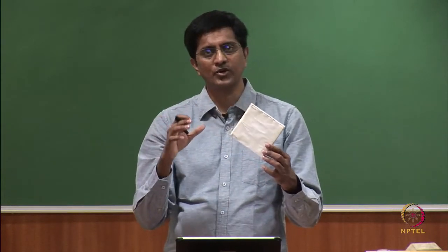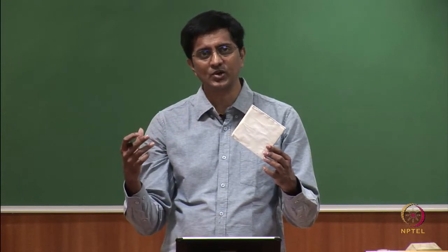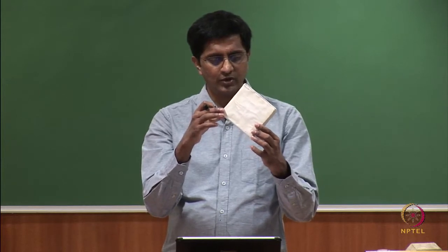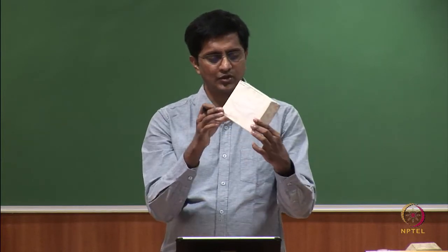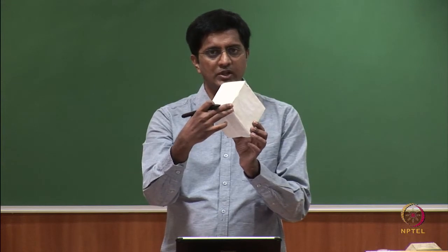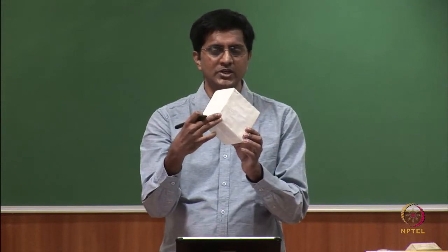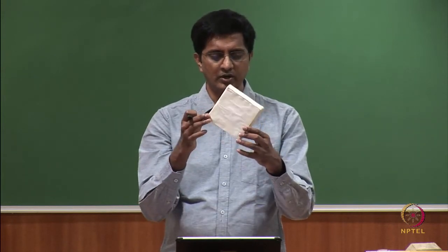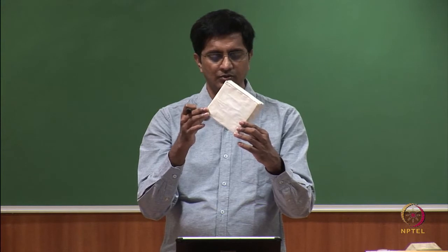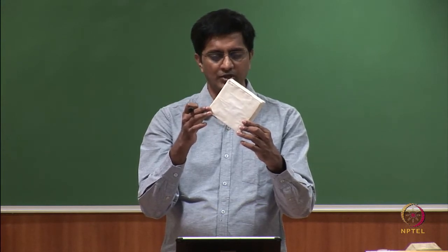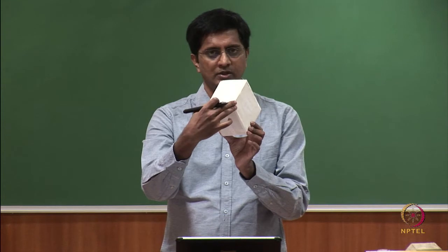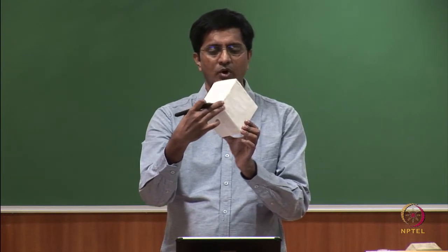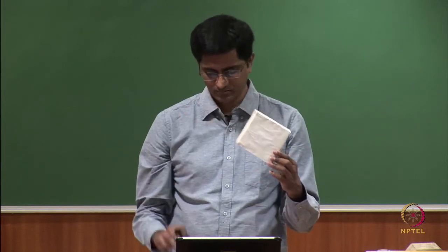Now, let us come to the final step, which is the actual question to be solved. After this single rotation we do the second rotation. Once you do the second rotation, will the front view shape remain the same or the top view shape remain the same? That is a question to be thought about. I can again show you. We are going from here, before rotation, to after rotation. Obviously, the front view does not remain the same. So, what remains the same is the top view.